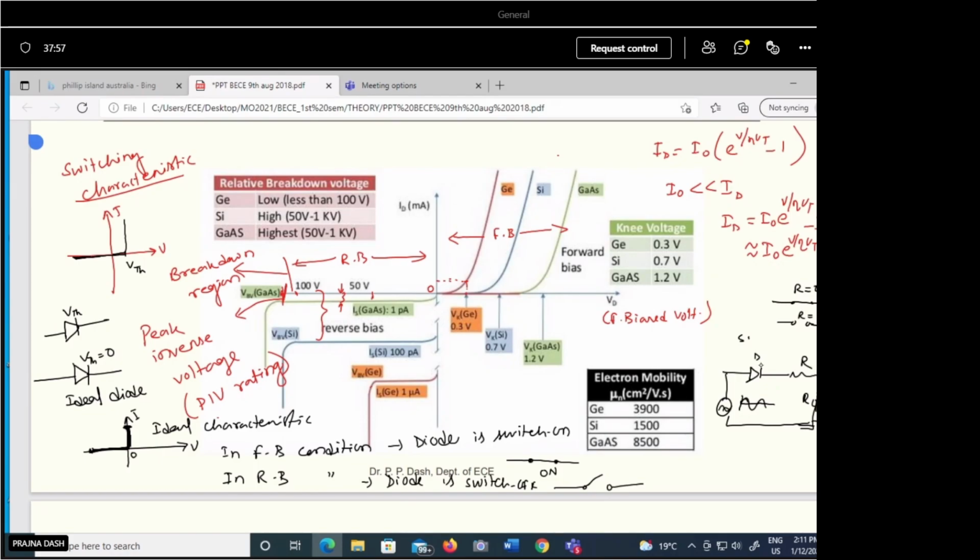When it is mentioned that the diode is a silicon diode, for example, written above the diode, then when the diode is forward biased we have to assume that the voltage drop across the diode is 0.7 volt. In that case, we can replace the diode by a 0.7 volt battery. Then put the other elements of the circuit and calculate the voltage drop across the load. We will solve some numericals based on this. So in this way you have to solve.